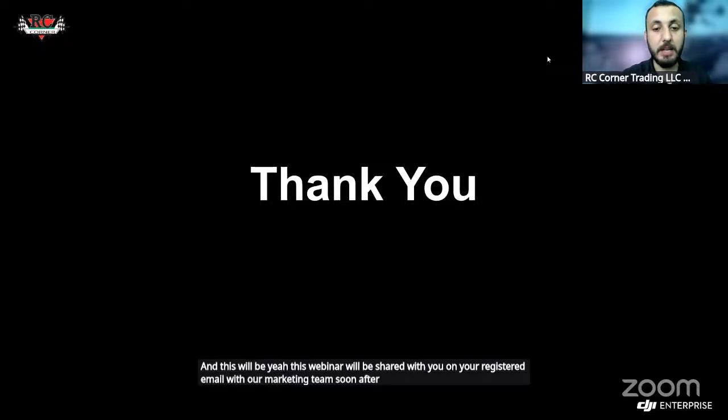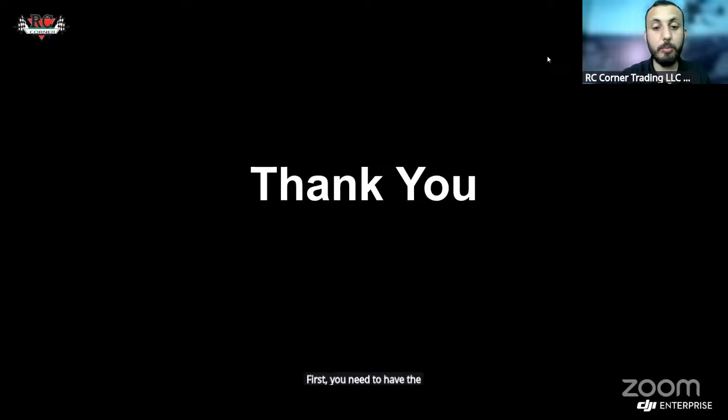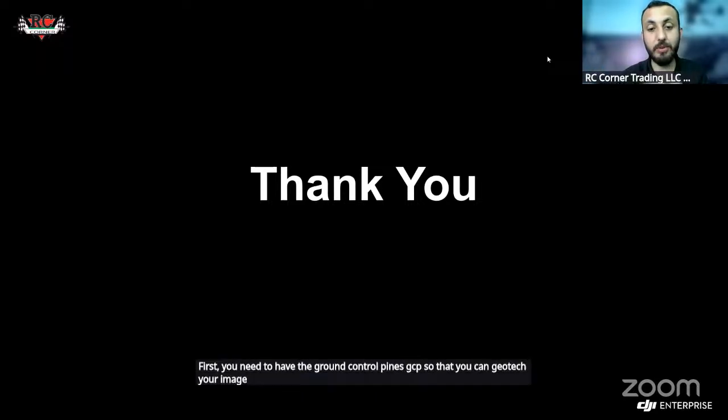We have one question: how can we improve the accuracy of RTK surveying for mapping using the Mavic drone as a UAV? You can surely increase the accuracy, and you have several ways. First, you need to have ground control points, GCPs, so that you can geotag your images to those coordinates, which are the original location on the ground. This will enhance your accuracy.